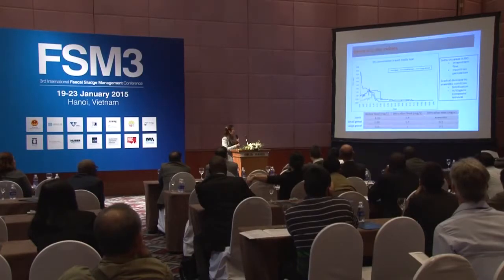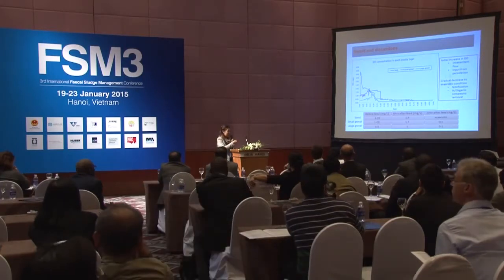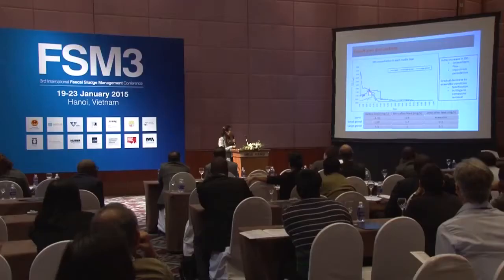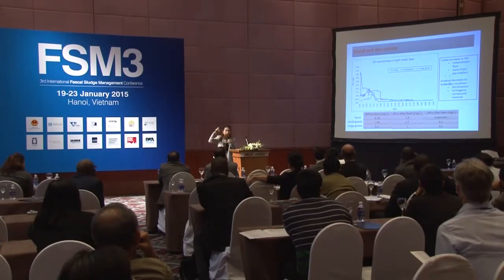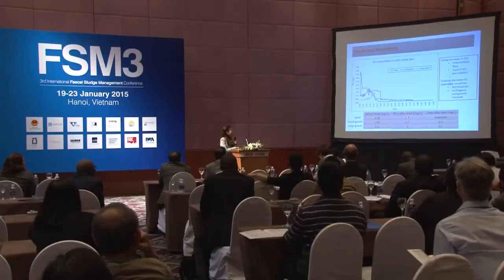Next, we would like to focus on nitrification and denitrification here. This slide shows you the DO concentration in each layer. The percolate of faecal sludge contains DO of about 4.5 milligram per liter. After feeding into the system, this one represents the concentration in the sand layer on the top part of the system. After 6 hours of operation, it goes from 3.4 to 1.9 milligram per liter.